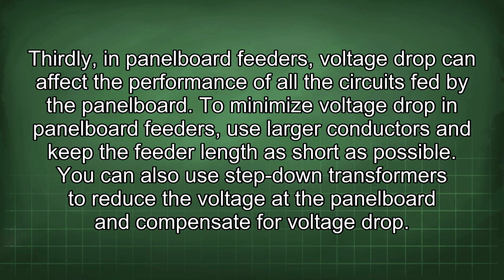Thirdly, in panel board feeders, voltage drop can affect the performance of all the circuits fed by the panel board. To minimize voltage drop in panel board feeders, use larger conductors and keep the feeder length as short as possible. You can also use step-down transformers to reduce the voltage at the panel board and compensate for voltage drop.